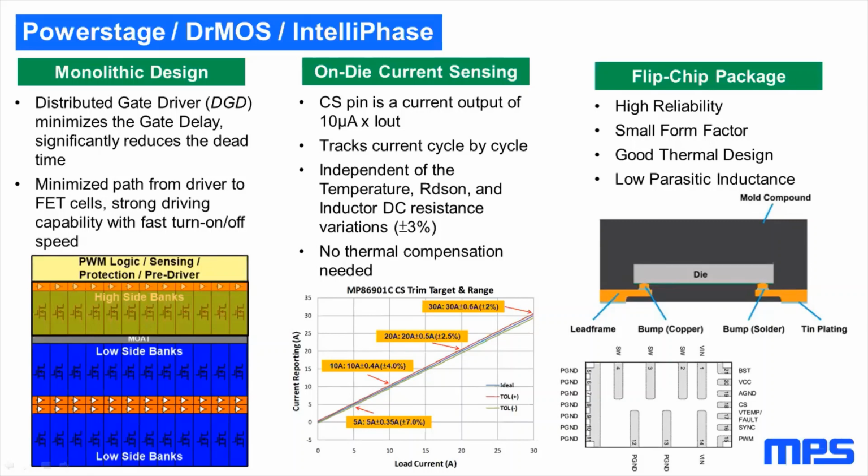These copper pillars have accurate and reproducible mechanical dimensions, which solder balls don't have, and this allows us low parasitic resistance and inductance. This, on the other hand, reduces the ohmic losses within the package, and due to the reduced inductance, it reduces the switch node ringing. Furthermore, this packaging technology is highly reliable due to these copper pillars. This has been proven when doing several thousand thermal cycles from -40 degrees to +125 degrees during automotive qualification of our parts.